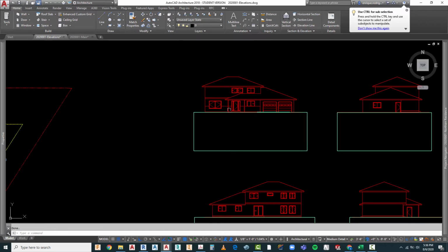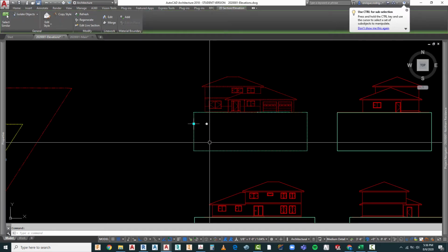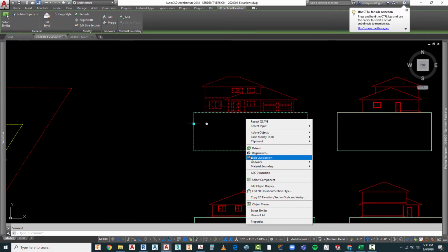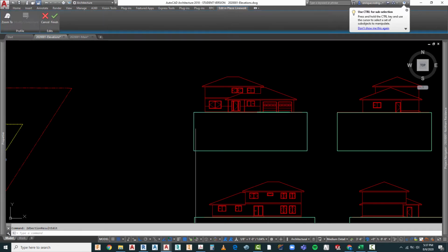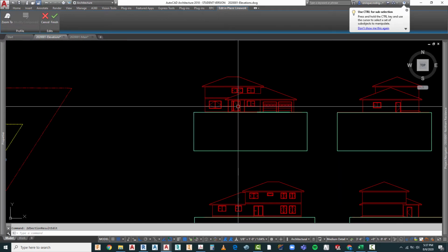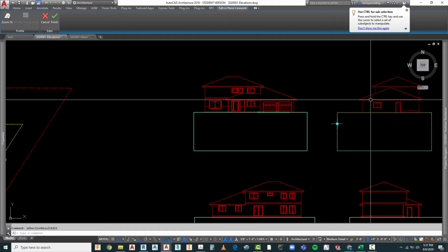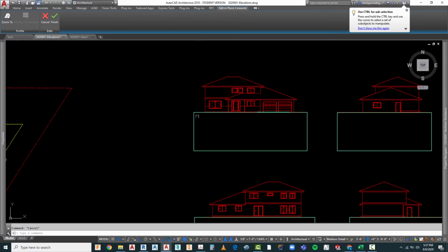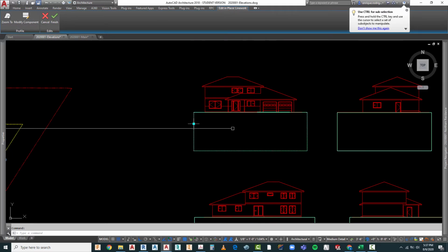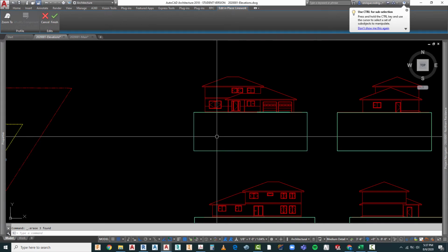So what we can do is highlight our 2D elevation section style. We're going to right click again, and this time we're going to modify it by going to, in the pop-up window, line work. We're going to go to edit. Before, when we highlighted, you remember everything lit up just like here. Notice how it's all one element. But in this one where we've done our modifications, if we highlight it, you can take a look at these items right in here. We can actually delete those items.